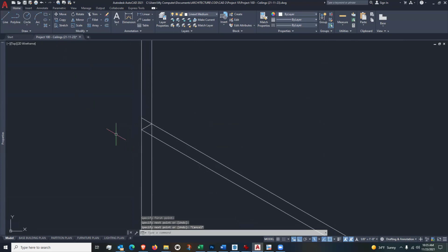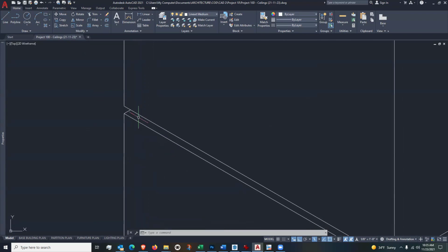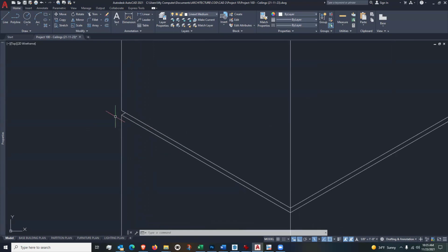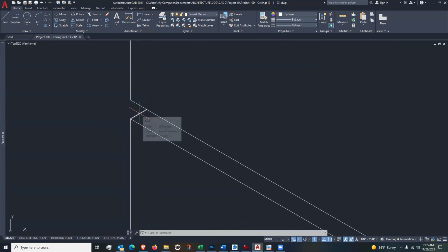Now I no longer need this, and I need to trim this here. So I'm just going to trim that. Now I'm seeing the top face of this bottom panel in my reveal here. It's cutting back, and it just happens to be back at 1 inch, so I'm not seeing the back edge of it. If I recessed it back only a 1/2 inch, then that line would be here, and I would see a vertical. But I'm not doing that.